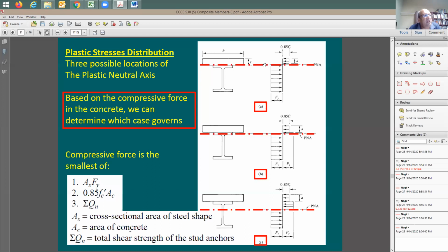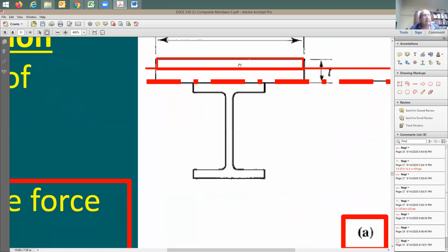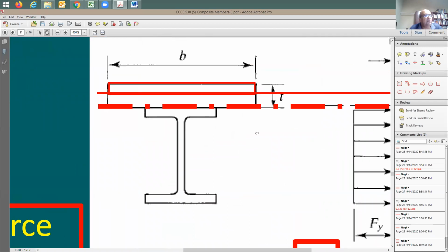So we need to push this neutral axis up here and only take this section of the concrete, and say the compression in this section is going to be equal to the 600 kips. Now, do you know this compression block depth? You're going to say, I don't have it. So I'm going to simply set C equal to T, very similar to what we have done in concrete design, and based on this, figure out the compression block depth a. This depth here, we're going to call it a.